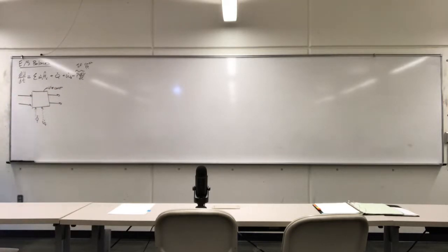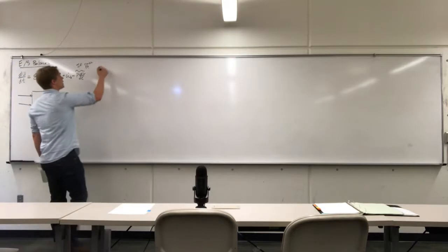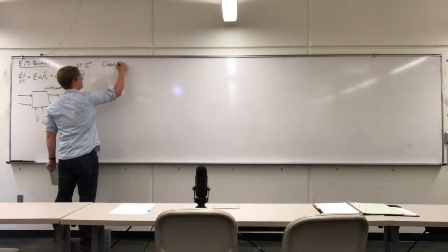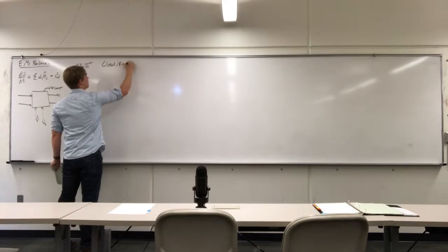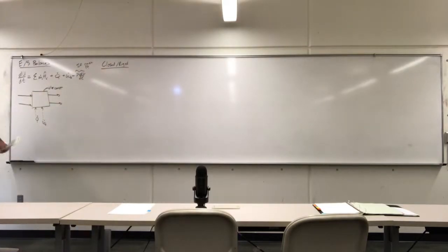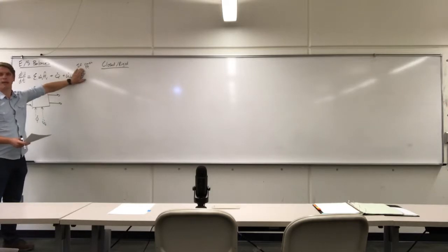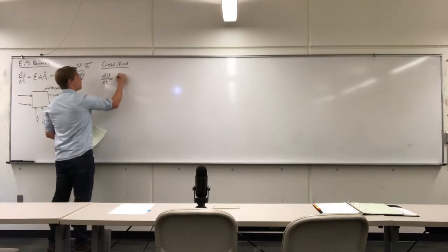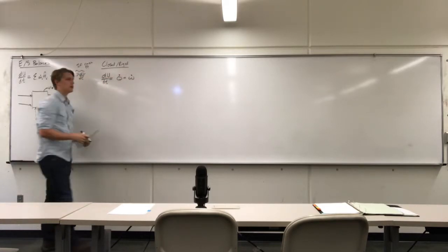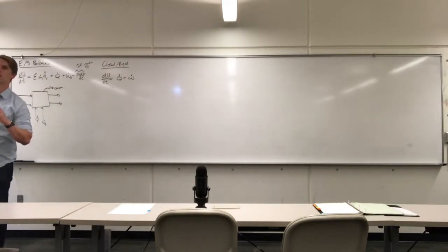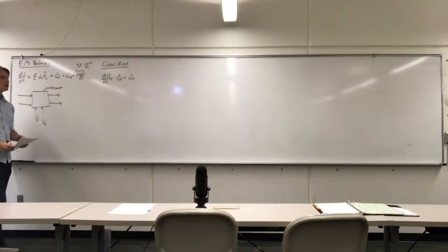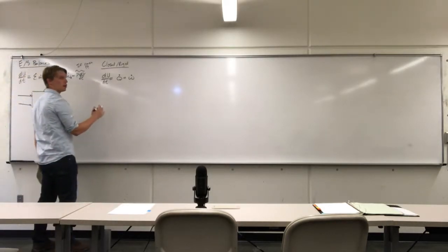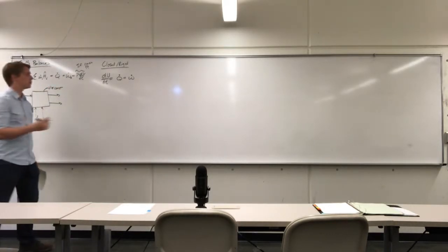So this is our general energy balance equation. Now we'll talk about a couple of quick assumptions or simplifications. Let's say we have a closed, rigid system. What do we cancel out in a closed, rigid system here? Mass goes away, and PV expansion goes away. So in that case, the change in internal energy of the system is only equal to how much energy is entering or leaving the system in the form of work or in the form of heat. So how we would write this then if we wanted to solve for, let's say, heat, for example.